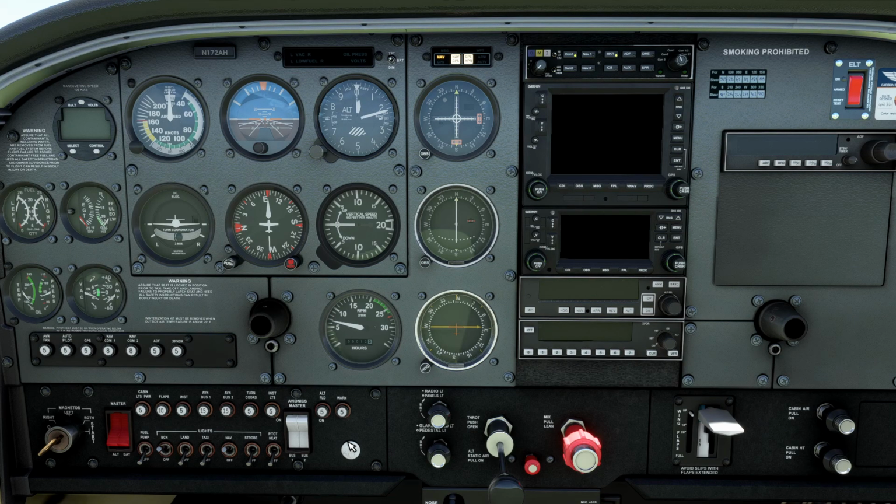If you started on the runway or in flight, the avionics master will already be turned on, and that will power up the autopilot. The unit goes through a self-test when it's first powered up. This takes just under 30 seconds to complete, and the autopilot is not usable during this time. It will do this self-test regardless of whether you power up with the avionics master or by dropping into your session in a powered up state.